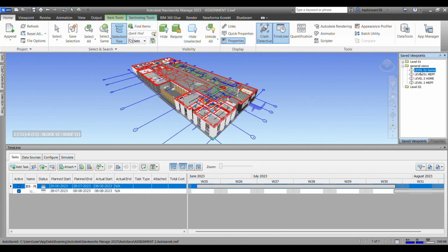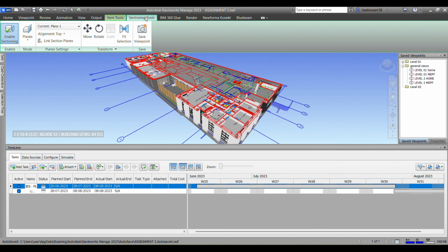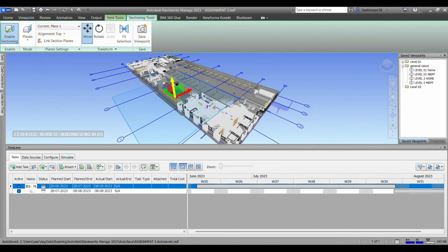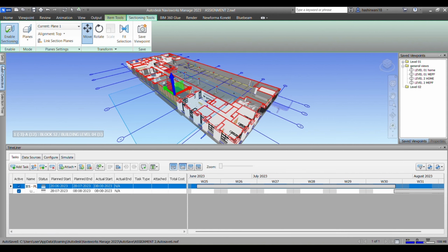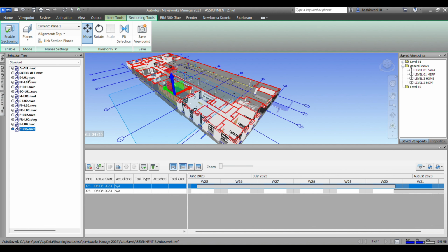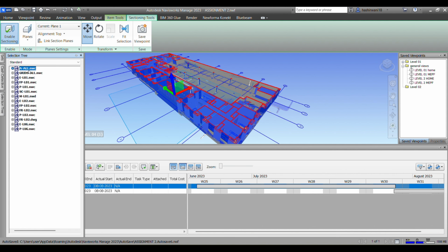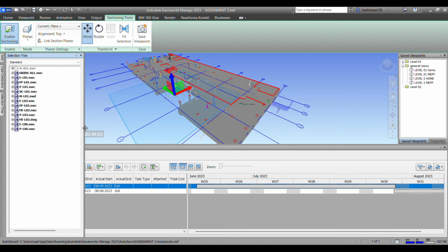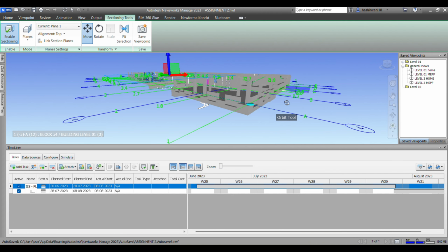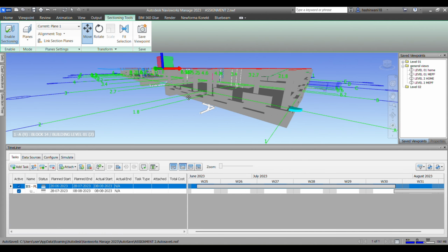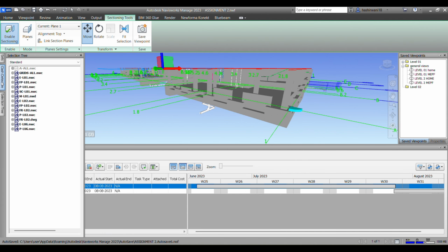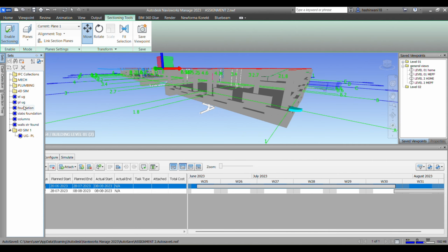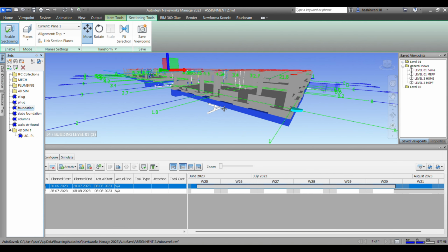If I go to my home here, and I go to the sectioning tool now, I'll activate the sectioning tool. Can you see here what I can do is I'll just turn off my architectural model, Control H, right? I've shown you guys. Can you see my architectural model is turned off? And if I go to the selection tree again, sets again, and if I select the foundation, can you see all the foundations have been selected? So I've created a selection set for this foundation as well.